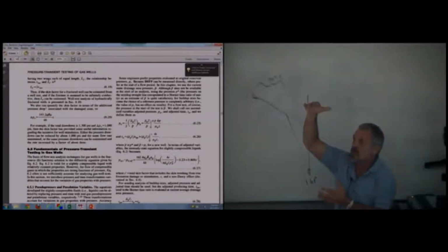Now, when we were first testing tight gas, doing tests to get a pre-frac perm, in this textbook they use the wording downhole shut-in device. That means in order to eliminate or minimize wellbore storage, not only did they run a bomb to the bottom of the hole to get bottom hole pressure, they ran a temporary packer in the hole to shut in the well at the bottom rather than at the top, so that you only have maybe 20 feet to fill up before you kill the well. The well tended to kill itself. Is that enough about afterflow?